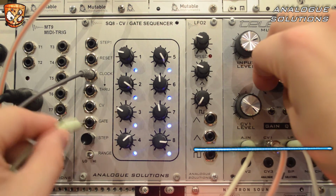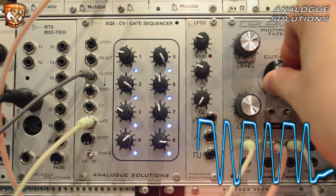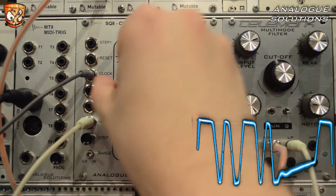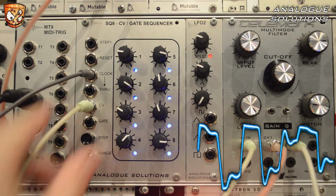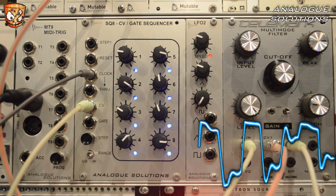As we've got the gate output, we can also create a second pulse-based waveform by pulling out some of the knobs to create a gate sequence, and this audio rate gate sequence will have a different sound to the CV output. So I'll take both the gate output and the CV output from the SQ8 and create a crossfading patch between the two audio rate sequences generated from the SQ8.